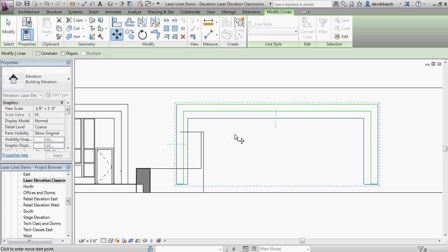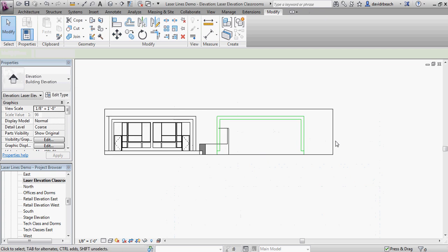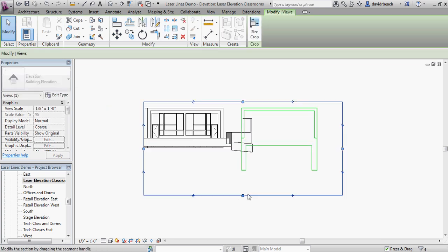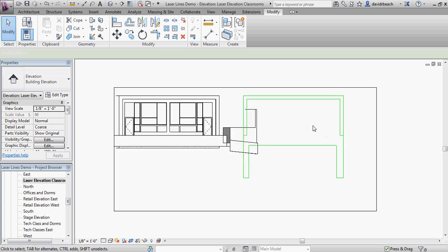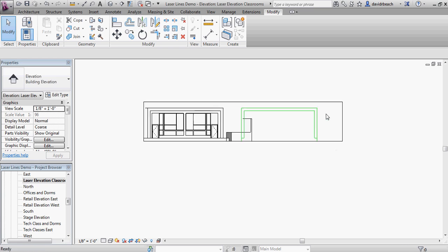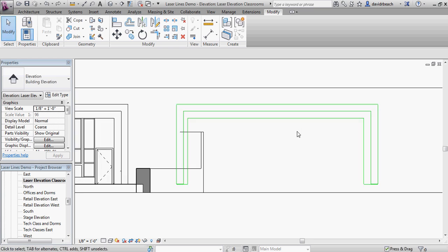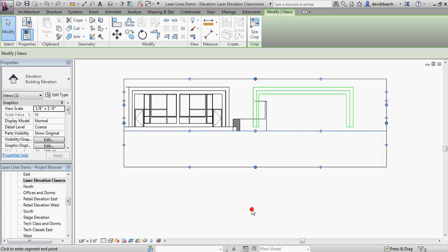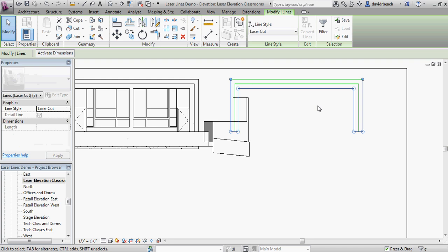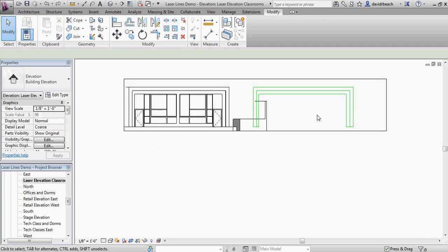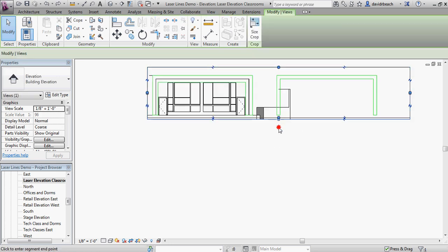However, what I also want you to see is those are actually two layers. So I'm going to move one underneath the other so I can start to see how they're going to stack up. Oh, and Revit did something that Revit likes to do to me. Items are kind of sticky, so as I moved that piece down, it actually stuck that top edge together. Let me undo that really quickly, just using Control Z. I'm going to pull this view down again, and use the Tab key this time. Actually, I probably shouldn't have put those on top of each other. So I'm going to Control Z all the way back.